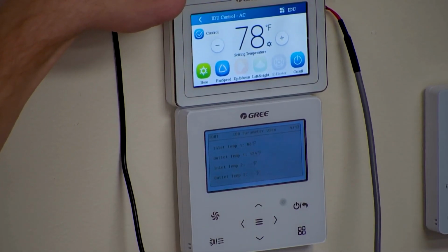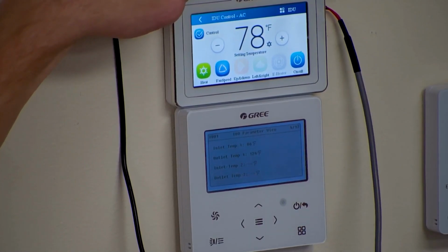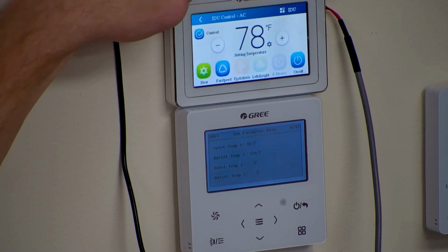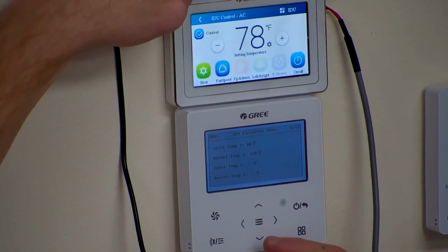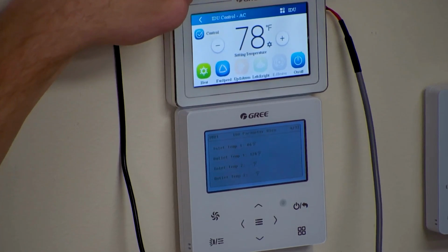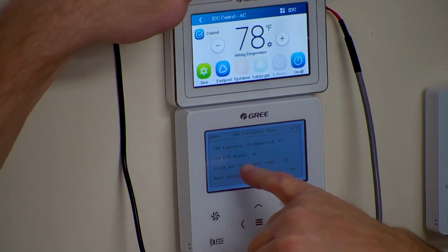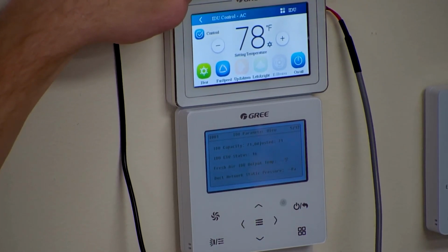Inlet, outlet temperatures. So if you've got a wired controller, you can actually go see this information on the wired controller as well. But if you've got all cassettes and all wall mounts and you don't add the optional wired controller, now you have no diagnostic information because you can't do this with the remote. This gives you some really good information. And it'll also go through here and give me the EEV step. Indoor unit EXV status, 16. So that one's a little trickier too, so let me point that out.